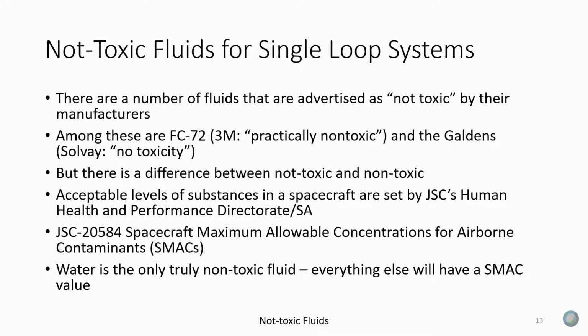So we talk about single loop systems. And so we're talking non-toxic fluids. Water is not going to work for a single loop system because you're not going to send water out to a radiator where it can freeze. It's just a bad idea. There are also reasons not to use water glycol mixtures unless you want to go to a stagnation radiator. And we end up with issues.